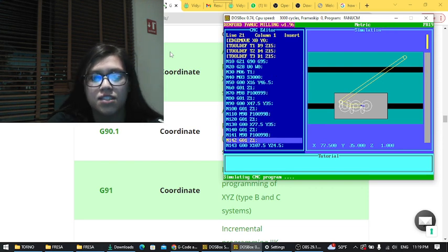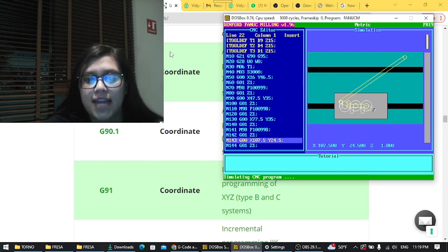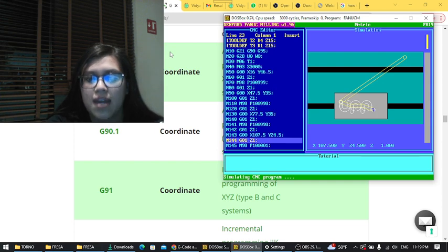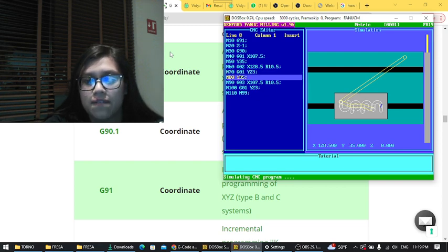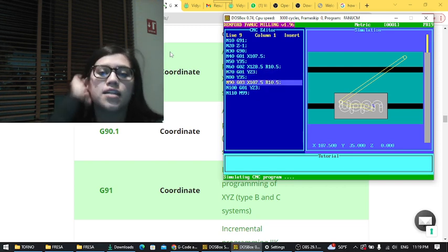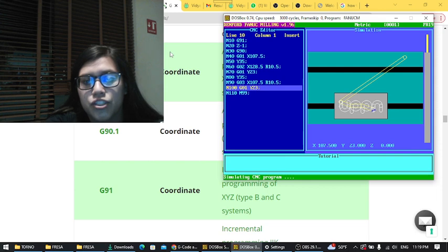We're going to pass on to X, and it's going to start on X107 with a height of 24.5. We go to the subprogram, as you can see. Now the height starts at Y35 as U, and the X starts on X107.5.